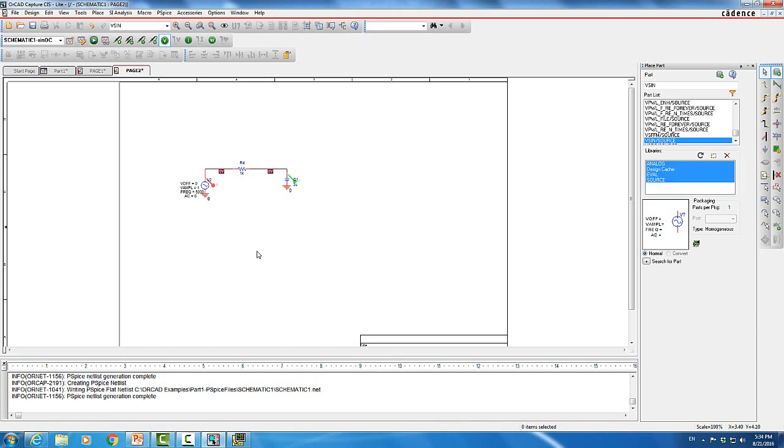Now for completion, I'm going to add a rectangular pulse here. So a rectangular pulse will show you what is the time required for the voltage to reach its final value, as the input voltage goes from 0 to 1, and if it goes from 1 to 0, it will show you the time required to drop down to its final value. Now this is also another important concept.